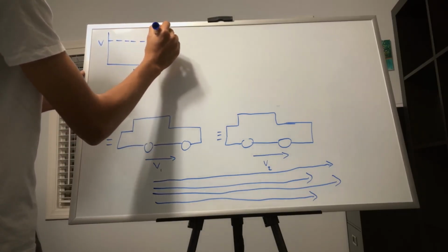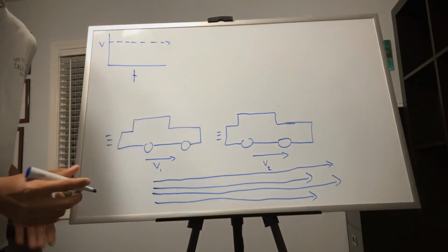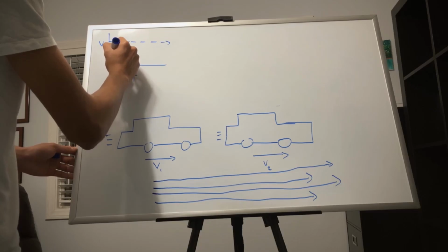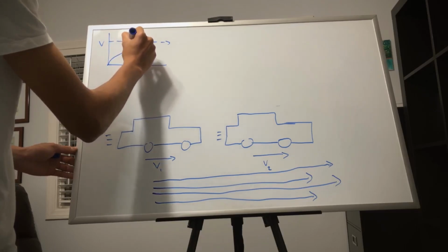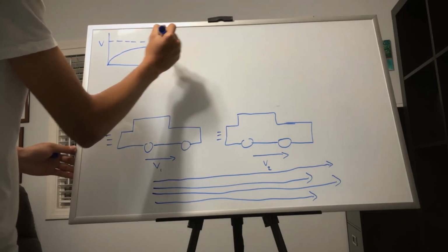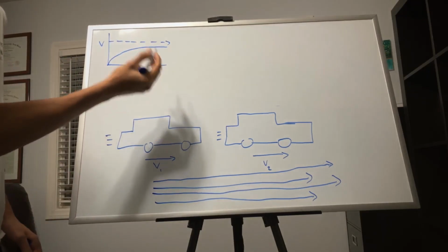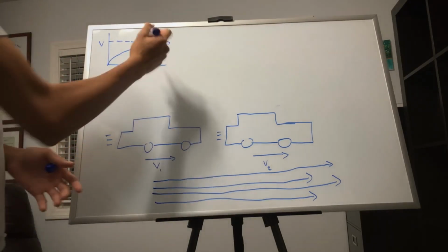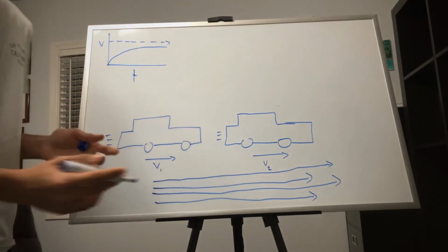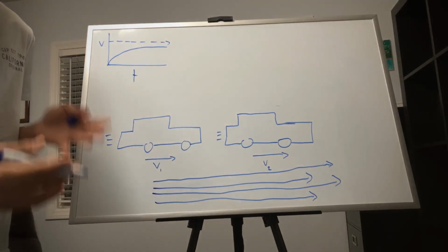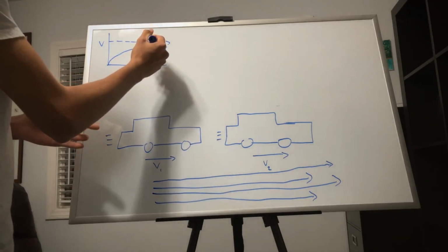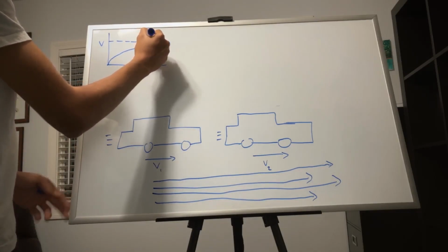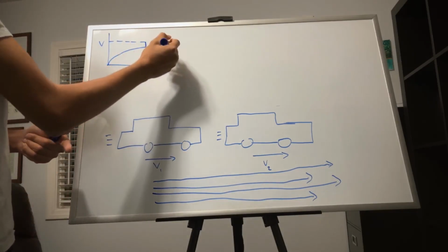A steady state error would look like our velocity reaching a point where our error decreases, but then our velocity settles at a point that's lower than our set point. So we have eliminated some of the error, but not completely. We haven't reached the speed that we originally wanted to reach. This is an example of steady state error, a steady error as time goes on.